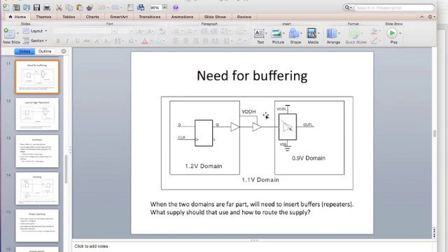Now, the problem of signal integrity is there even without level conversions and so on. If you recall from the last semester, you have this problem of crosstalk, right? So typically there will be a separate signal integrity check which will be run. You have to do that signal integrity check once you've placed and routed the design, to ensure that the crosstalk and coupling and all that will not affect the functionality. So that has to be done anyway.